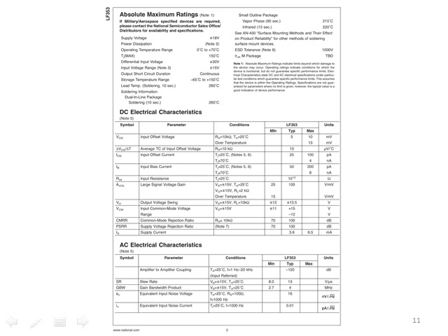This is an example of a data sheet for an operational amplifier. I won't go over this in detail. These are the types of things that you should have already experience with at this point in your careers. But when you pick an operational amplifier, the first thing you do is go to the data sheets to look at the particular operating characteristic that's most important for your design. If it's a low input noise voltage, if it's the bandwidth, the frequency response, the driving current, the output impedance, etc., you can check it in the data sheet.